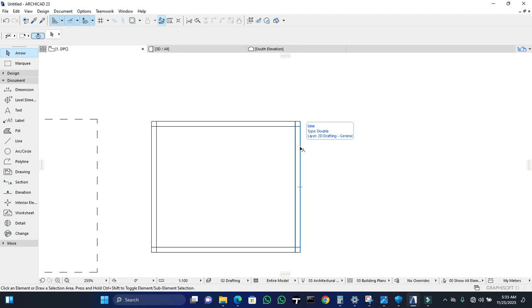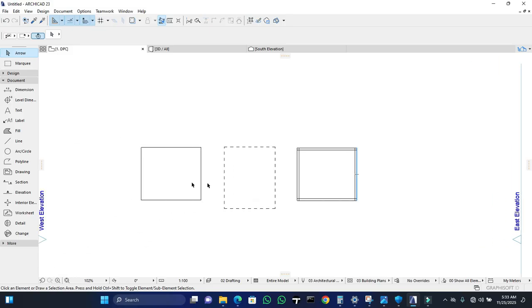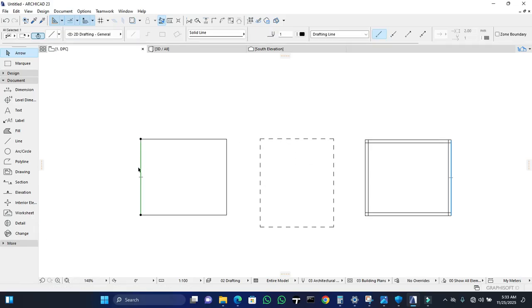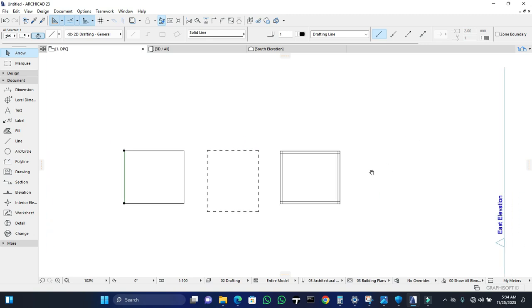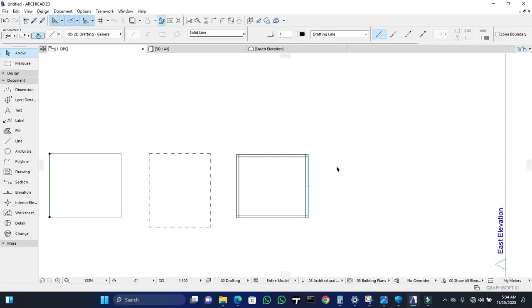You don't know the distance, except you customize a line by yourself and you make sure that the distance between the 2 lines is to your desire, to specification. Other than that, we don't know what the default spaces are, so don't use it for walls. It is even preferred you draw this line and copy it to the specific distance you need before you decide to use it for walls and other detailed elements of design.